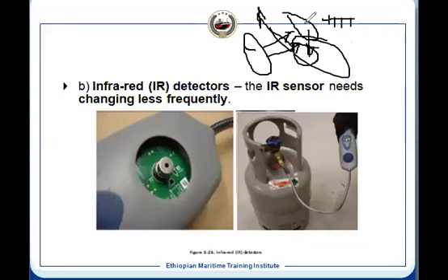So this sensor is measuring that particular wavelength which can be absorbed by the refrigerant. This is supplied by the instrument only, so we have control over it. We know which wavelength of infrared ray we have supplied. Accordingly it is measured, and it can directly give you a reading of whether there is any leakage and what level of leakage, small leakage or large leakage, on the display. So this is another way we can carry out leak detection.